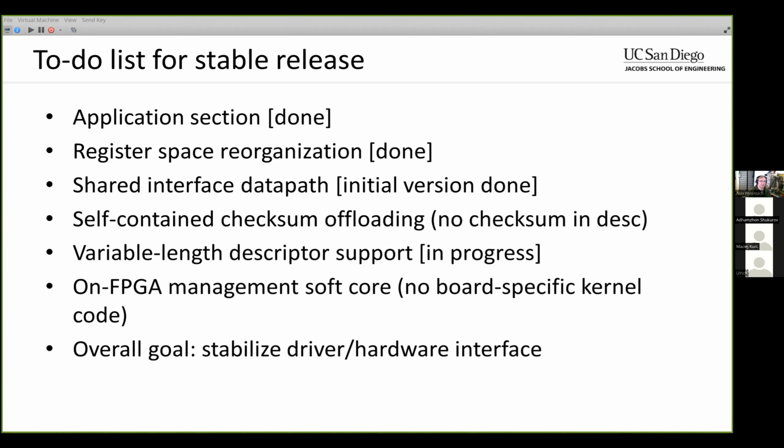Okay. Well, so that definitely points to some sort of a problem in the checksum computation code. Yeah, and interesting that it only affects Intel devices. So that points to it could be some sort of a synthesis issue, maybe something about that code that the Quartus tool doesn't like. Yeah, we also thought about that. We kind of roughly checked the code and thought about it, but up until now we did not see anything obvious, or I have to say, our colleague did not see anything obvious. We didn't expect anything obvious though.